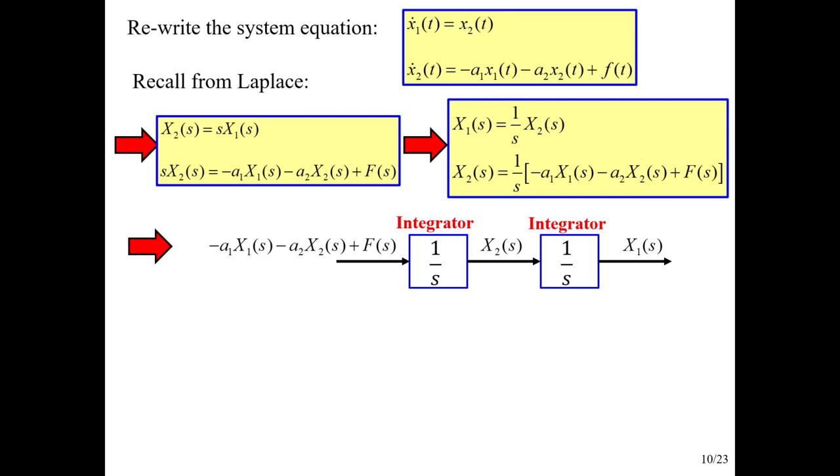So if we just look at this from a block diagram point of view, remember we said way back in that original note set on state space, we said, oh, a good choice, not the only choice, but a good choice for state variables are the outputs of the integrator boxes, 1 over s's. And so here's where we've put our state variables.